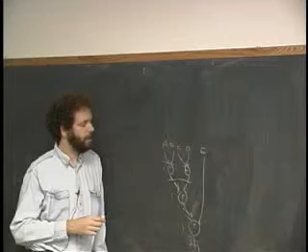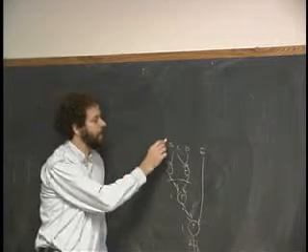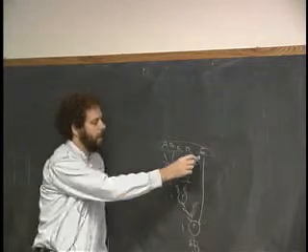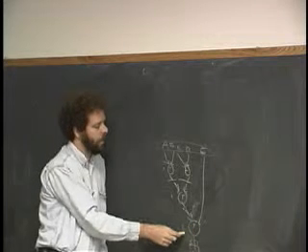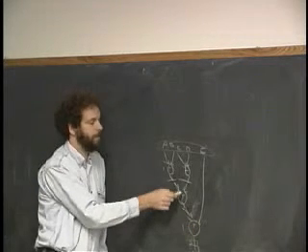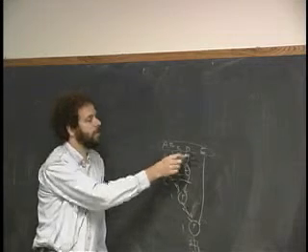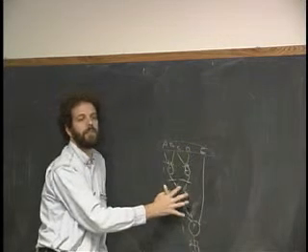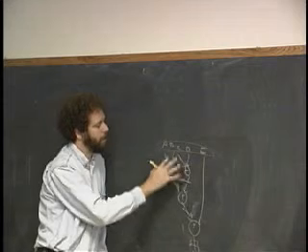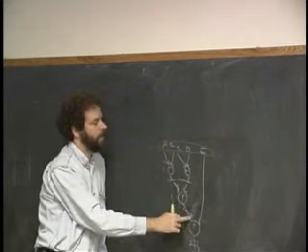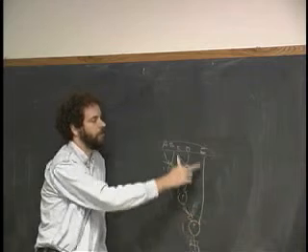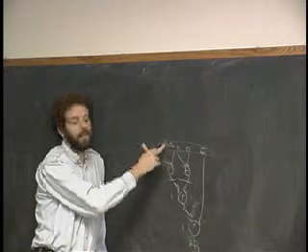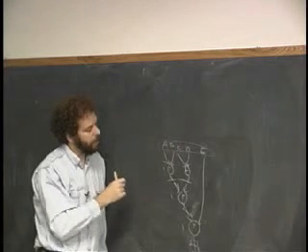You think this thing's a pipeline that's going to work? We simultaneously feed A through E to here, and we hit the clock. What happens? E goes directly to here and combines with a result that is 2 clock cycles old. In other words, E races ahead of the data values A through D and gets out of sync with them, so that when we finally do get A through D added up down here, we're going to be adding those to E that's 2 clock cycles ahead of these. And that's bad.